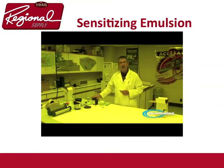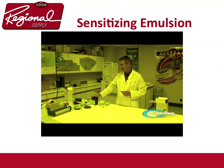Set this aside for 1 to 2 hours to let it degas, and you're ready to go. Now you can coat your screen. That is how you mix up a diazo-based emulsion. And it's the same for all diazo-based emulsions, whether it's straight diazo or a dual cure emulsion. Thank you.